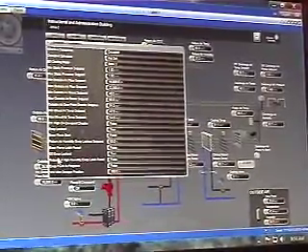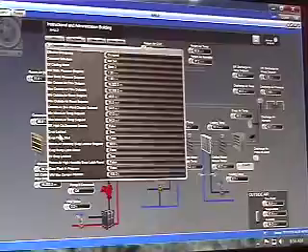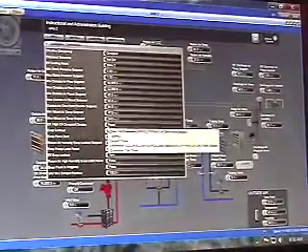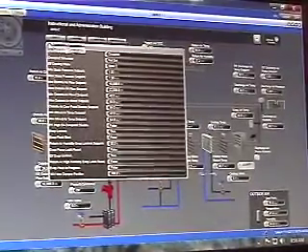There's something called an evap lockout right here, which is set to true. What that means is that there's a couple things. If you don't want the evap media to run, say it's going to be really humid outside, it's going to start raining or something like that, I don't even want it to run. If you turn that evap lockout to true, it'll skip the state. Instead of going 2, 3, 4, it'll go from 2 to 4, from 4 to 2. It'll just skip over that.